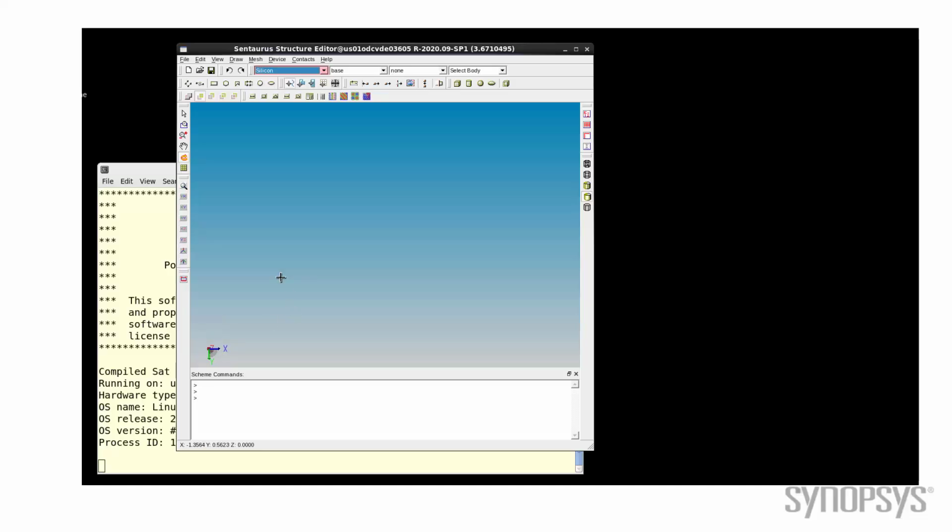To ensure precise alignment and prevent gaps in the structure between different regions, activate Exact Coordinates mode. The pressed button indicates that the mode is active. To start the process of building MOS device structure, we define silicon substrate using rectangular region drawing tool.